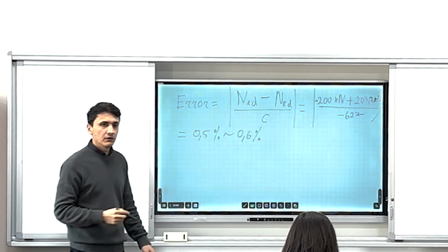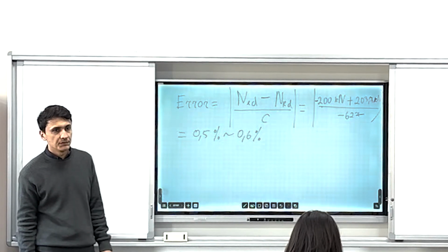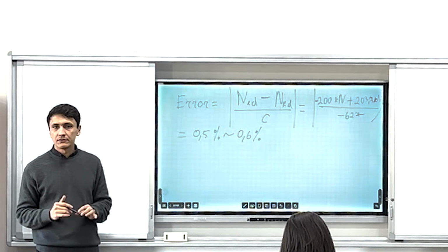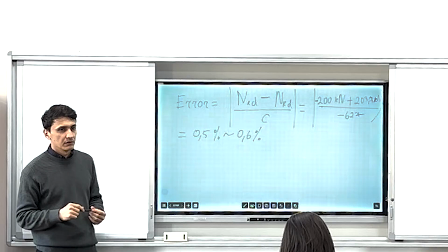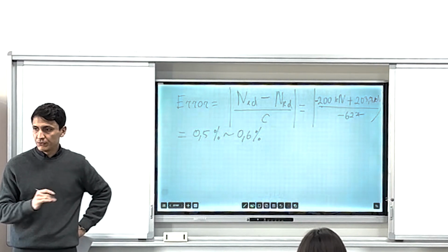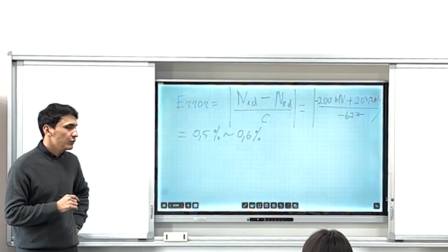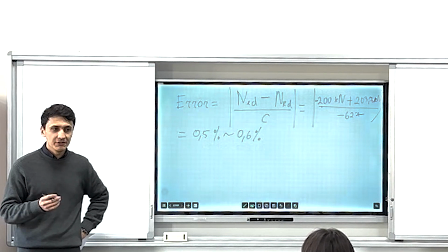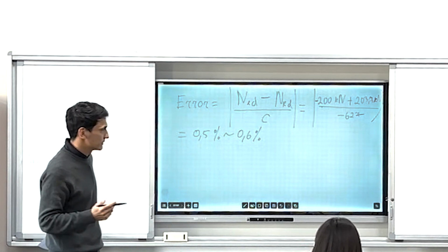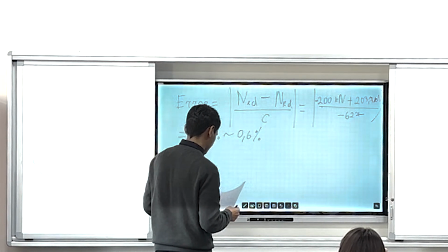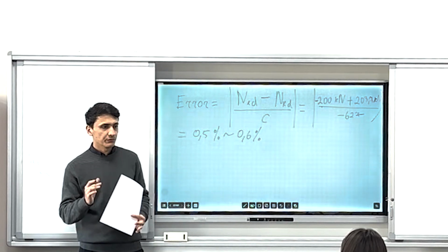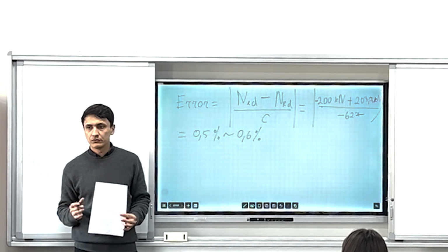So now, if the error is less than 1%, it means you can take the already applied value of the neutral axis. It means the values in your calculations are correct. Okay, let me finish. We didn't finish yet. Our goal was to find the yielding bending moment. We found the forces, not the bending moment. We should find the yielding bending moment around the neutral axis.